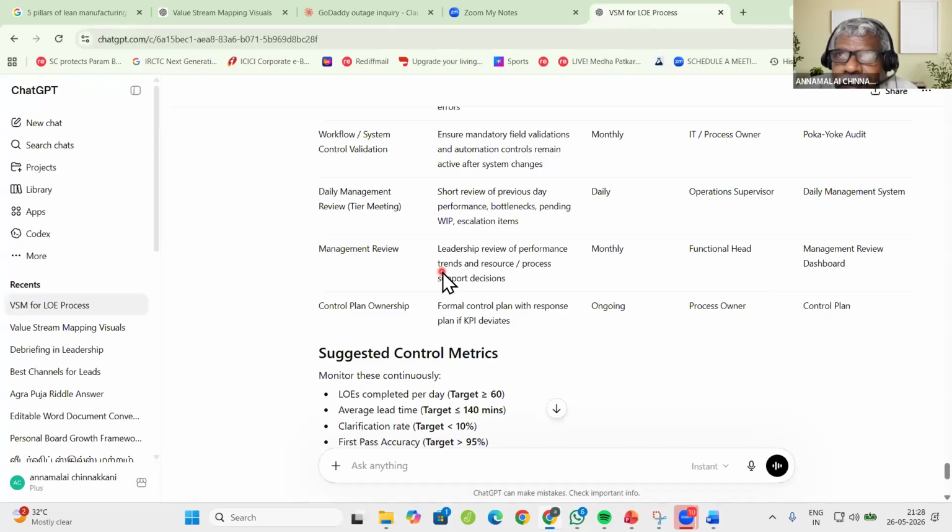And then after all the improvement actions are implemented, again, you do the future state mapping. Since you have taken action on that, you will be able to meet the customer demand. Then if next time you want to increase the customer demand by maybe 5% or 10%, again, you know which is the choke point. So at each cycle, try to identify one choke point, maximum two choke points. Try to work on the improvement plan and implement it. It will take around every 2 to 3 months. You do the value stream mapping, then you will find the substantial improvement you will be able to achieve.